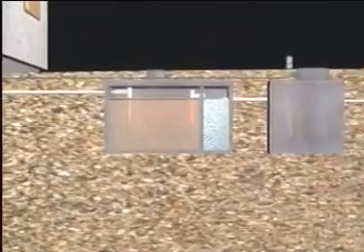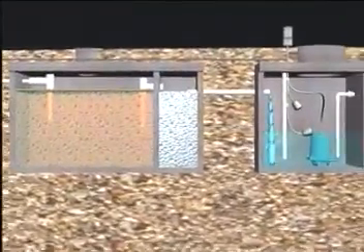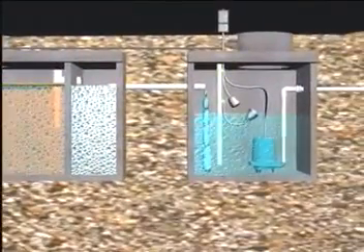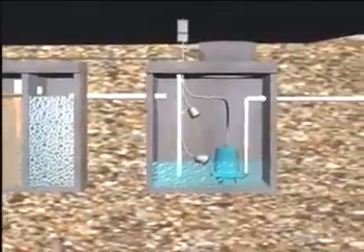In this typical residential system, liquid waste discharge from all household sources flows into a central gathering point, a septic tank. There, after settling or other treatment, the effluent is collected in a pumping chamber and pumped to a lateral field via a pressurized manifold or distribution box.